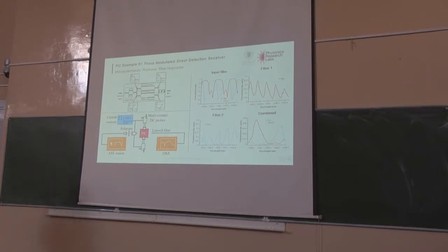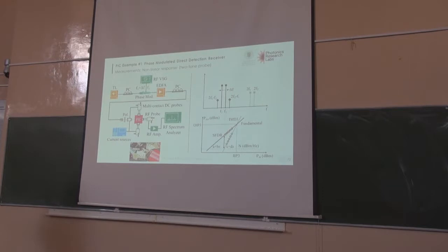Okay? So this is the filter response, and we did as well a typical two-tone probe response to characterize the nonlinear response of the RF system. If you are familiar with RF engineering, you've seen this, for instance, in amplifiers. And you use two tones at the input, okay? And then at the output, what you get is actually the two tones, but also the intermodulation tones, and also the harmonics there. So the intermodulations that fall near your tones are the ones that you use to measure the relative amplitude and to state what is called the spurious-free dynamic range, okay?